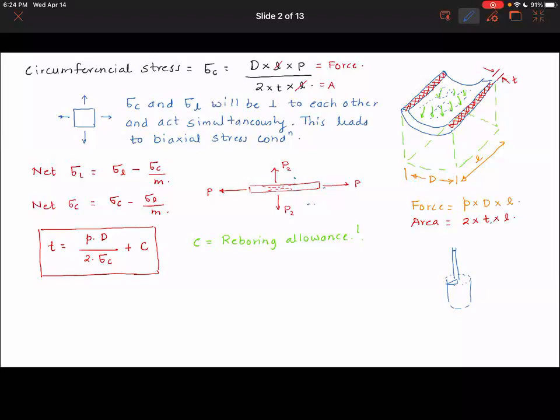Sometimes, if a significant amount of reboring is required, they rebore and then put a liner inside the cylinder. Initially the cylinder did not have a liner, but it got worn out, and then you basically add a liner. Now, why is all this jugglery needed? Because many a time, and this is important, the cylinder is part of the cylinder block. It's not an isolated component.